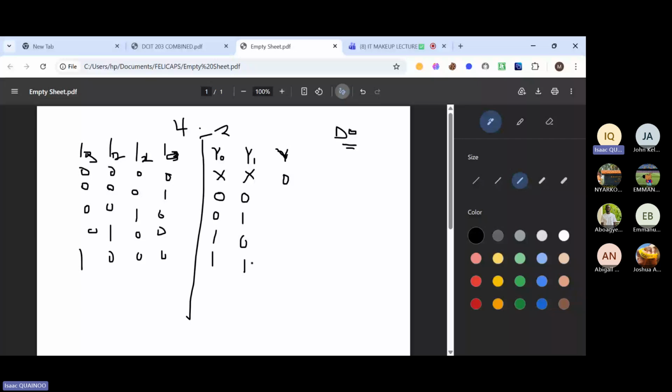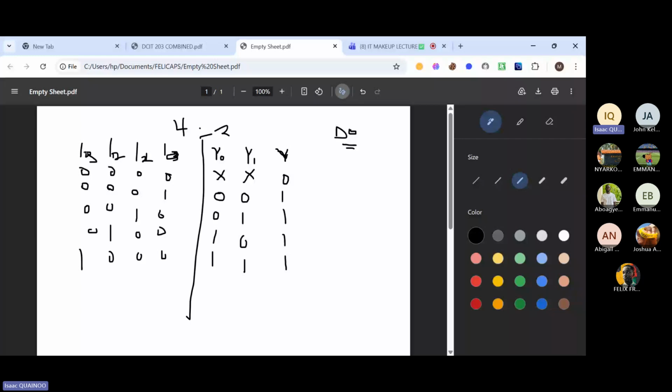So here, the reason why the circuit is able to function normally is that we apply 1 to our priority, which functions as our enable in this case. So now, let's study this carefully. We said that in a priority encoder, it assigns priority to our highest input, which is the one closest to our MSB. Here you see that this is 1, this is 1, this is 1, this is 1.